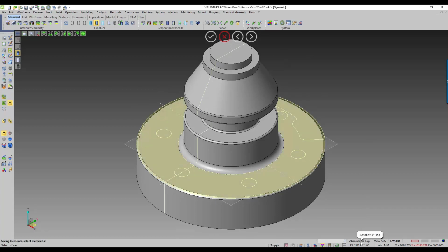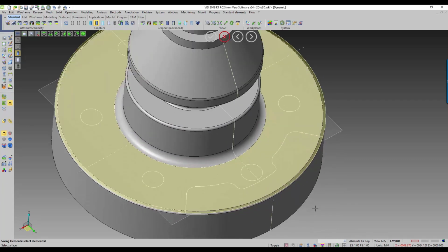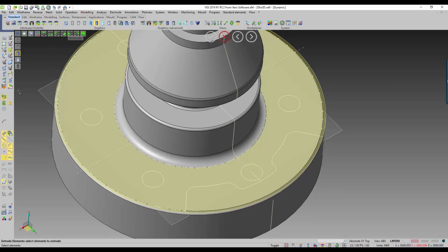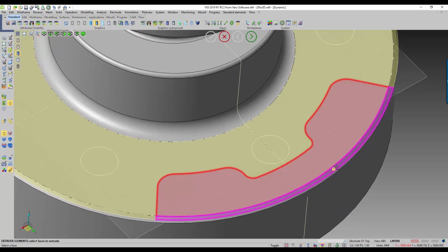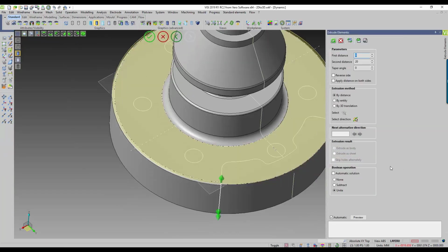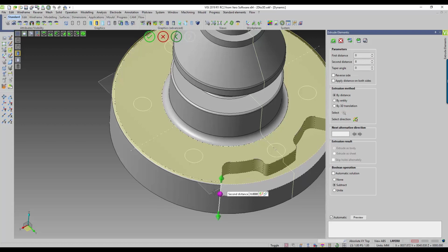So this is good for accessing modeling commands, creating something from a solid. It makes it quicker. So now as you can see, if we rotate to the XY top, you can see how that highlight's going to change. And now we can choose faces from this current work plane area. So if we choose extrude, I can choose a face or the faces based on those closed areas. I create this into a pocket or a boss. So in this case, I'm going to create this into a pocket, subtract it out. I can choose the distance I want to keep.